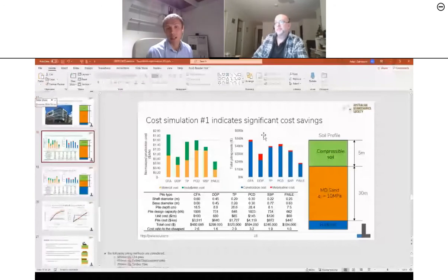So there's skin friction along the shaft, and there's also bearing acting against the upper helix. In both cases, void can be formed. If the ground under the bottom helix yields and the bottom helix moves down, we know what the plunging failure of the base is. If the upper helix goes up, we still measure the force, so we know what's the lower bound of the resistance of the pile, because we know that it's more than what we use to expand the helixes.